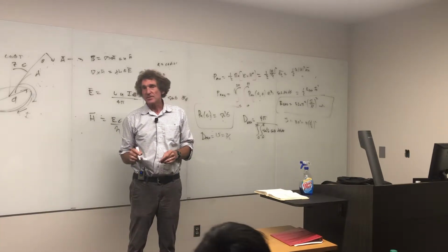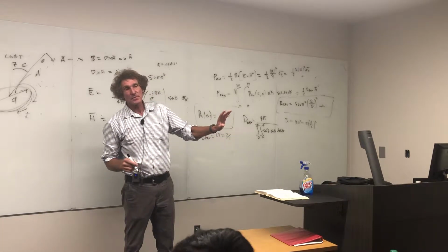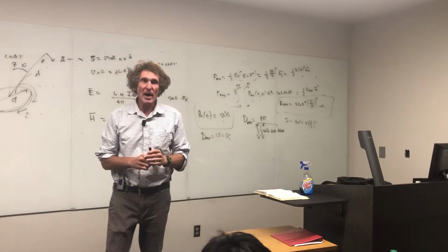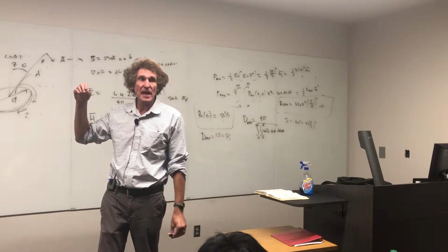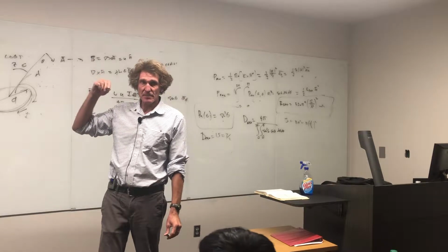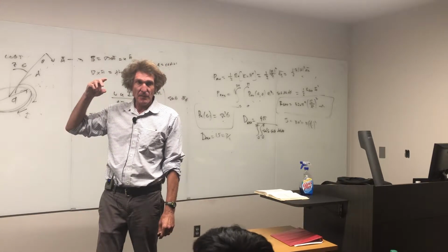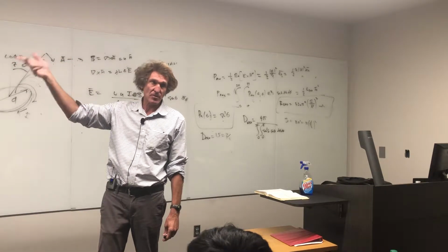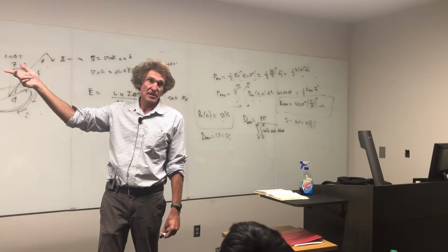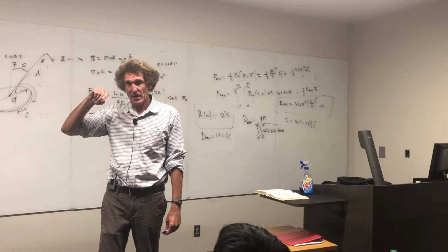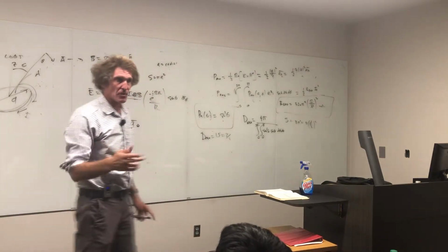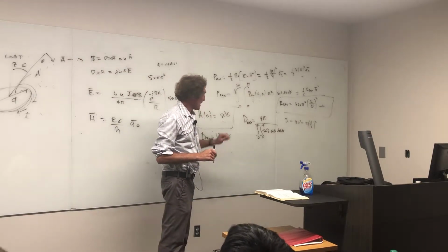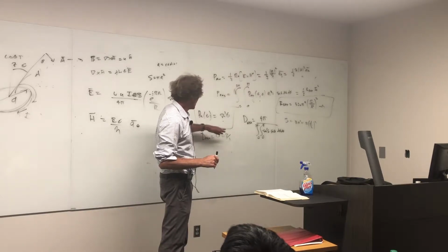Now, if I seem like I don't really care about this, the formulas for this stuff come in a variety of different forms, but usually what engineers take from us, they know how to get it if they need to go through first principles. They would get A from the current, and they would do these crazy elliptic integrals and get a series expansion of them, and they would do it. They'd find A, and from A, they'd take the curl of A and get H, and then they would get E from the curl of H. They'd take the curl of H is equal to j omega mu E. You know how to do that. That's a lot of work, but it'll get the same bottom line result. And the thing you want is radiation resistance, directivity max, and the pattern, which is sine squared of theta.